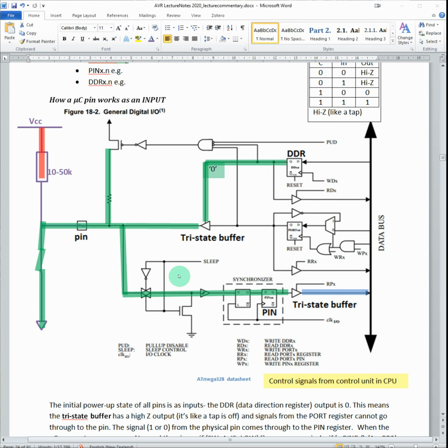So what we have here is the ability to put it into sleep mode. We use this inverter here to deactivate this, well, it's almost like a little multiplexer, but it's only got one input and one output. That pin is also used to power up this transistor, which clamps this input to 0, which means there's no possibility of any changes on the input pin making it through to the synchronizer and using power. An interesting little application of some switching and logic to reduce power.